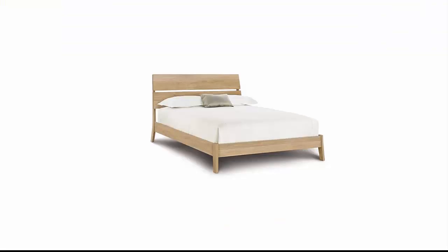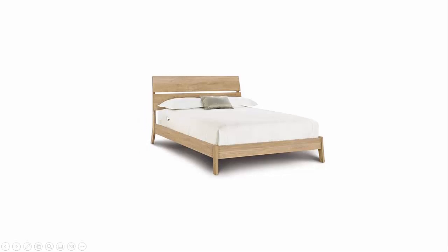Now in the bedroom we have a bed. Mostly it's only the bed. Maybe you have some dressing unit, a small wardrobe, okay, but the major portion of your bedroom is occupied by the bed itself. So here, 0.8 meters will be too high for me to measure the lux levels. Instead I would prefer to measure at the bed level. So I would measure at 0.5 meters, that is the height of the bed. On this level I'm going to measure the illuminance level.